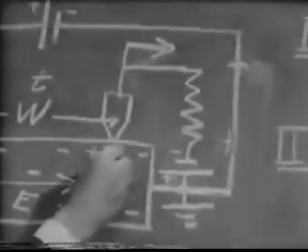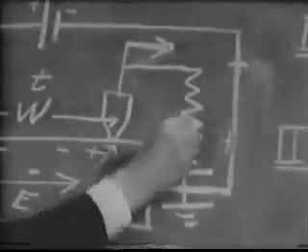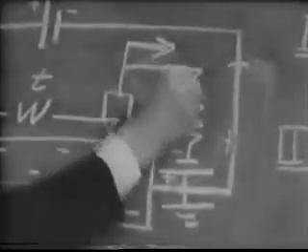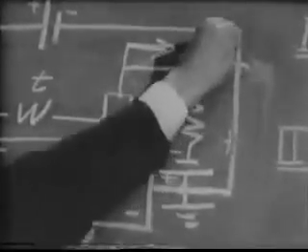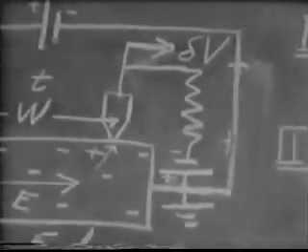Some of these holes are collected, and their current flows momentarily in this circuit, producing a positive voltage signal, delta V, and upwards deflection on the oscilloscope. In the detector circuit, which Bill just described, we use this 22.5 volt battery to reverse bias the right-hand point.